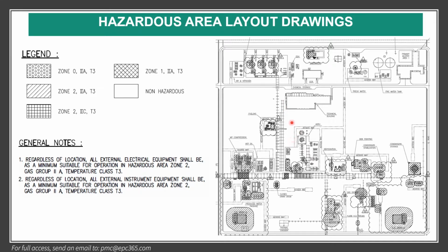And if there are doors around here, they should have an airlock. So you have to be very careful. Even if you should not just say that, okay, the hazardous area is on here, these are safe. You have to look at the restricted area and the LEL, how far it goes in case of a release in your process area.